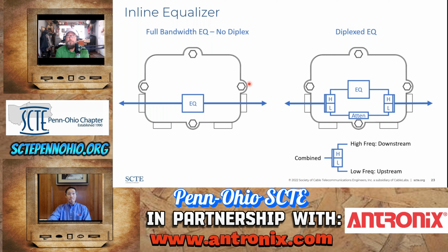This equalizer goes all the way down from 5 all the way up to the highest frequency of operation across the whole frequency band. So these are becoming more and more important, I think, to be identified as systems may want to upgrade their return path to start to approach symmetrical upstream and downstream speeds. Most of the legacy inline equalizers that have upstream conditioning through the diplex filter feature were mostly sub-split, from years past.